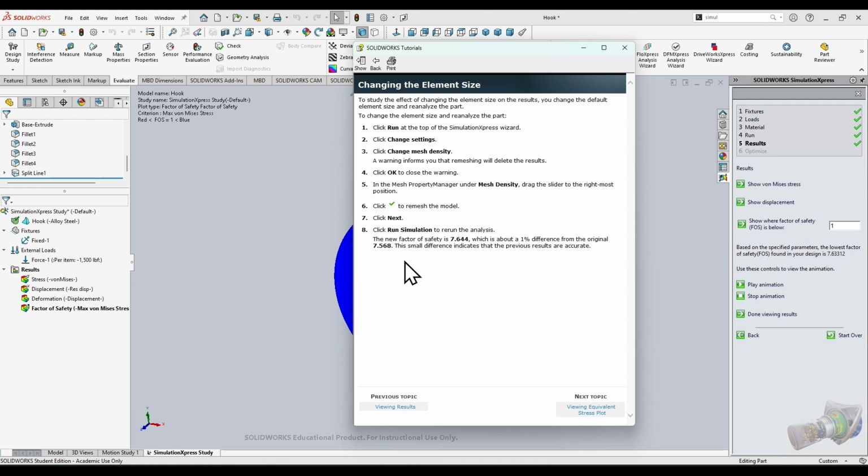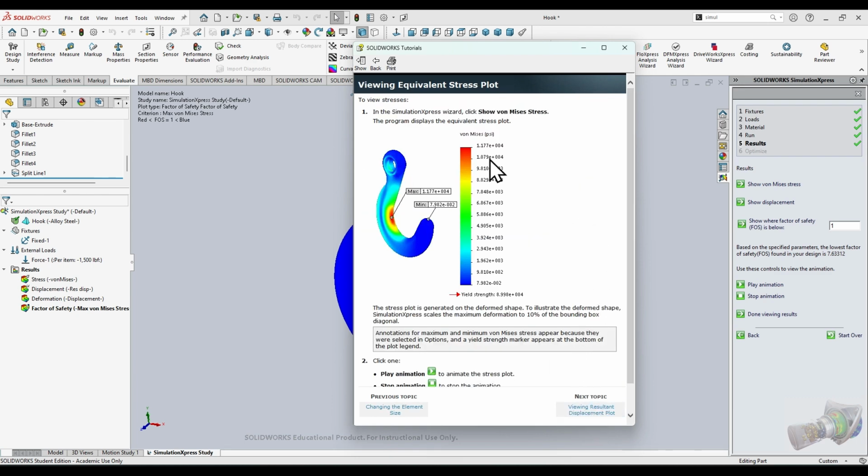So you can make the math 100 times harder than the complexity that we had already started with, because it's already a pretty tight mesh. Even when we use a coarse mesh, that's way more complex than we can do by hand. When we do it by hand, we're like cavemen. The computers definitely brought us forward a lot. So even using a coarse mesh on the computer actually provides a great understanding of what's going on inside the material as part of its stress and whatnot. So this is just letting you know that we can make the math a lot harder for the computer as well, and it's really only a 1% difference. So it's kind of up to you whether or not you use it.